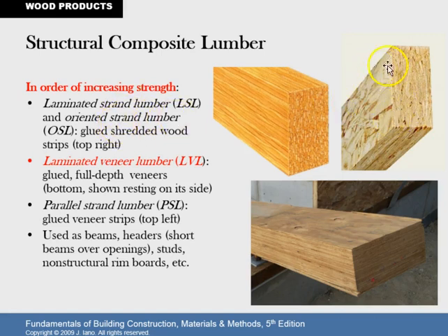So, two different names for what we're seeing here. These are essentially scraps, like wood chips, that have been glued together. So, gluing shredded lumber together. Very, very efficient in that it's not wasteful. Very little material is wasted in this process. Laminated veneer lumber: glued full depth veneers.